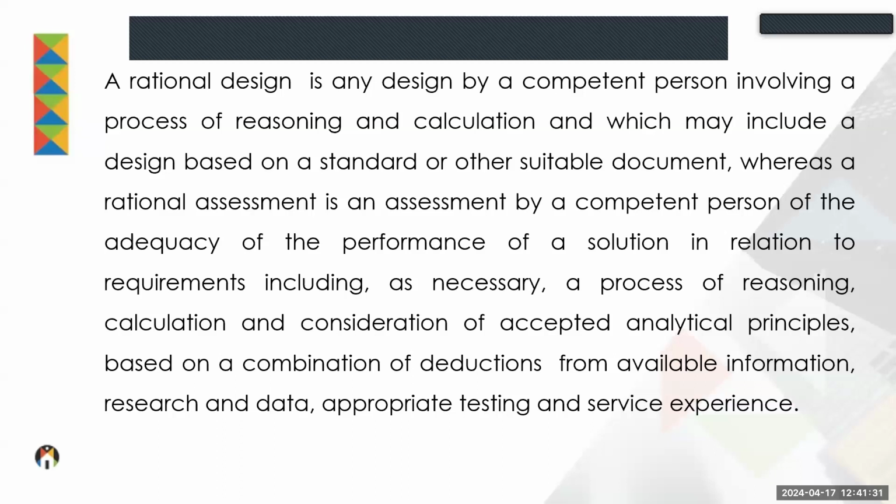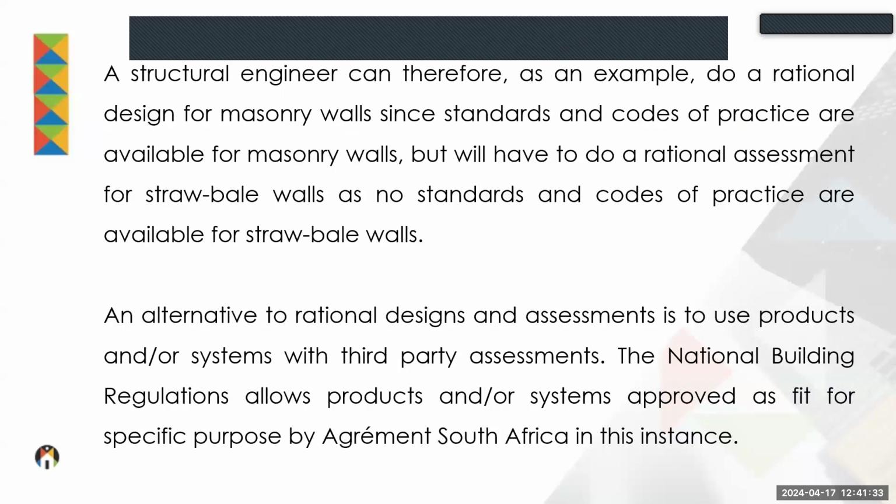Example, structural engineer. I do not comply with the masonry wall requirements as stipulated in Part K, the deemed to satisfy. My distances are much longer, my heights are much higher. So I go to an engineer, he uses the standard for masonry brickwork, and he does a rational design based on the performance requirements in there, and he proves that whatever he did will satisfy the structural requirements of that masonry wall.